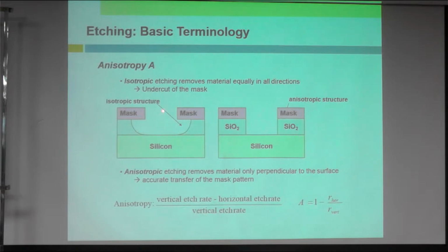So because the chemical will go in, firstly it will attack here on the surface area, but of course once it goes here, all directions of this SiO2 will be attacked, will be etched by the chemical. So from here onwards, it will go all directions.